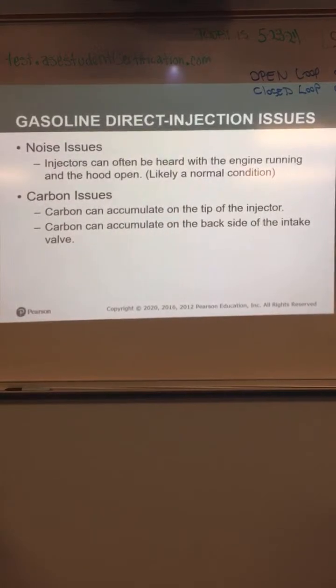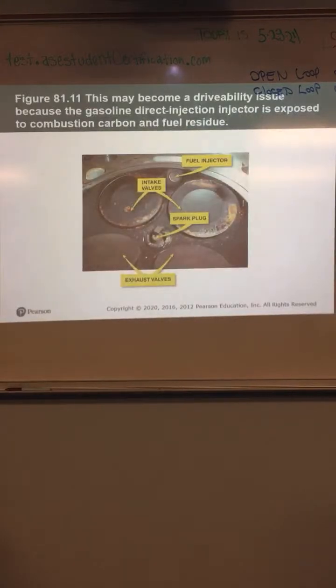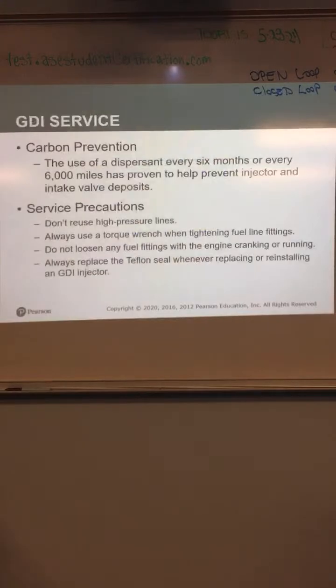If you notice, engines have dampening devices on them as far as noise goes. They all have the covers to make them look good because they're not typically very attractive without the covers on them. They will have some sort of noise dampening things because fuel injectors tend to get noisy on those types of engines. Carbon can build up on the tip of the injector and on the backside of the intake valve. That is one of the disadvantages. Could cause a drivability issue after a while, but hasn't been too bad that I've noticed.